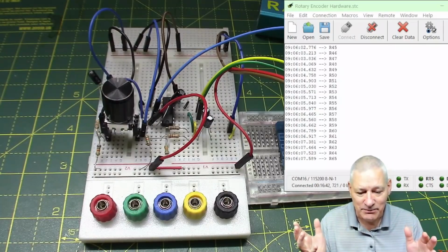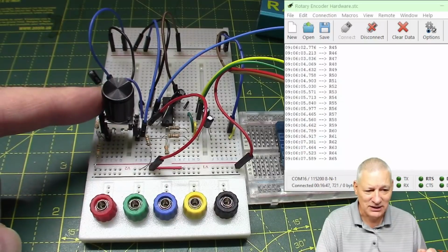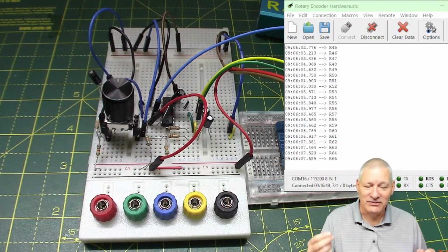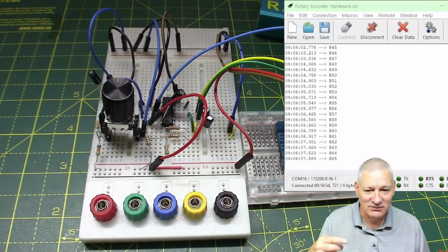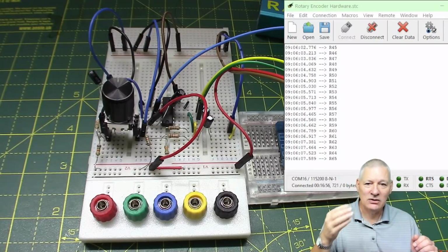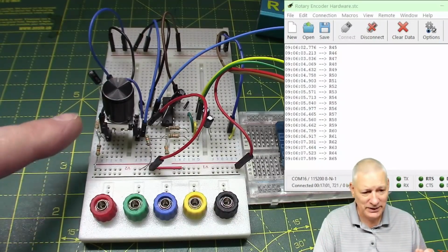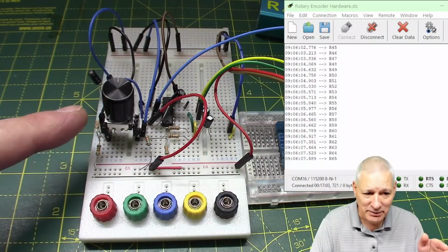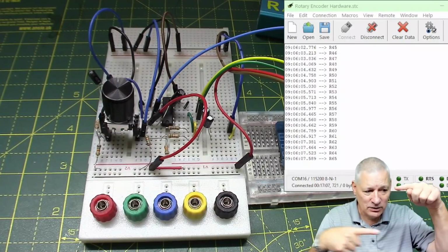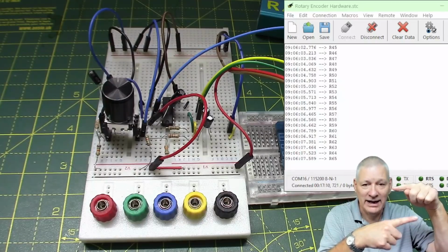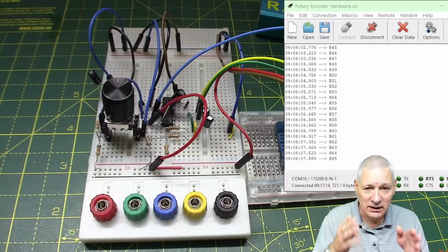I've investigated a bit. Basically, the mechanical restraints within this rotary encoder are such that if you turn it faster than that, apart from the severe wear you'd get, of course, spinning it very fast, they can no longer guarantee the integrity of those wipers. There's two pins on here, as you know, pin A and pin B, and they're out of phase by 90 degrees. So as one goes high, the other one stays low for a bit and then goes high later, which is how we can detect which direction we're turning this knob in.